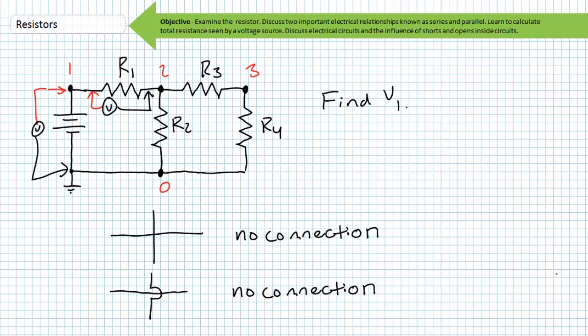Consider another scenario in which clarity is desired. Perhaps you're in charge and you're the one responsible for building, testing, and troubleshooting a circuit. You could use a confusing mishmash of unrecognizable symbols. Or no symbols planned at all. Or you could perhaps use letters to identify nodes and numbers to identify components, or vice versa. You could have a plan. This isn't a universally followed practice though, and you've got to, as they say, deal with it. If you're building a circuit, you have control. Make it easy on yourself and your lab partner and establish clarity up front. Imagine how well lab will go if you know what you're doing and you're organized.